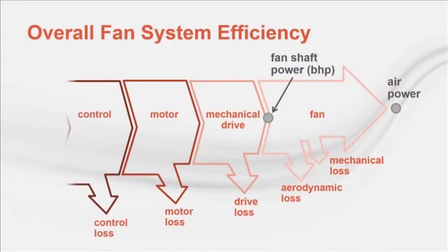Finally, there's the efficiency of the variable speed drive. A motorized impeller uses an electronically commutated motor that is very similar in operation and efficiency to a VFD. Like a motor, variable speed drive efficiency is a function of the load. The nearer the controller is to full load, the more efficient it will operate. The integral variable speed drive is engineered to match the EC motor and ensure that the combination is as efficient as possible during normal operation.